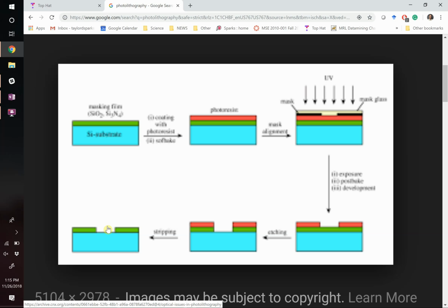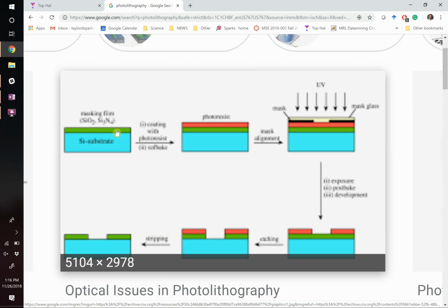But you're going to do something to put your dopants in a certain spot on your crystal, so only certain parts of your silicon conduct electricity. And the rest of it doesn't conduct very well because it's just intrinsic silicon. And when you wipe all the stuff off the top of it, now you've got channels, right? So let's see if we can see a picture of that.